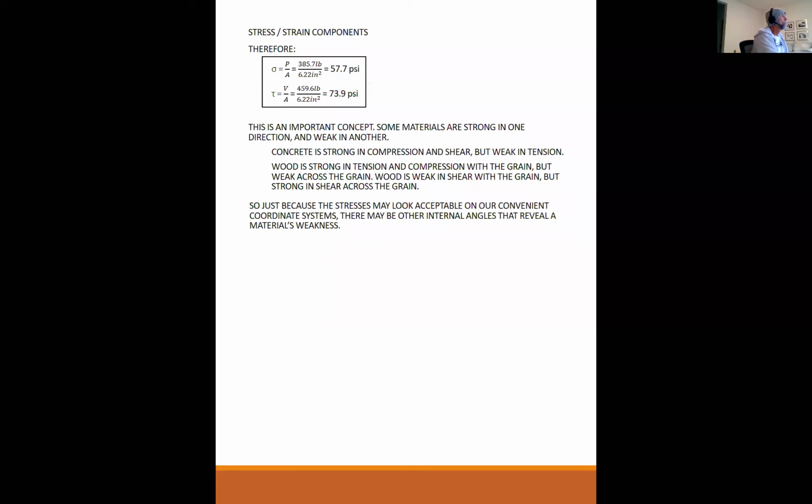is learn how to find the stress on things that are more complicated than just something in uniaxial tension. I won't go into this at great length, but say that you have a steel beam, like a wide flange like that. What we're going to do in the future is look at just a little element of this beam, like you just went in there with a plasma cutter and cut out a little segment of it. Then we take that segment and blow it up, and look at the stresses due to the loading of this beam that might be applied to that little element. So I might have some compression in the horizontal direction, and I might have some shearing on this little guy, like so.